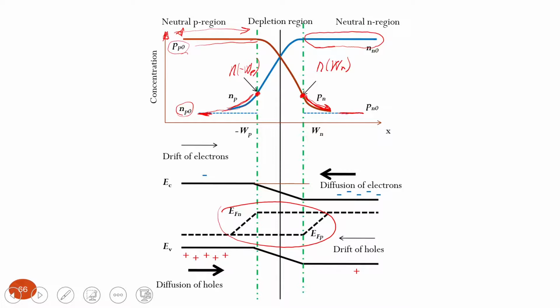Sorry. Could you please elaborate on this again, like on these linear drops, I mean, in the depletion layer region? In terms of energy, you say these linear curves in the depletion region. You mean here? Yeah. Actually, they are kind of quadratic, yeah, but for simplicity we just do it this way because it's easier to show.